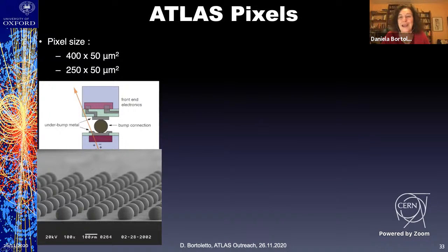And that's why we are trying to develop detectors where this process doesn't happen, that are called monolithic detectors. Here we have a part of the detector that detects the particle, readout built in silicon, and then a silicon readout chip. So we are trying to do together in the readout chip, produce the particle and read it out in the same point, so that we don't have to do this bump bonding, which is very expensive.